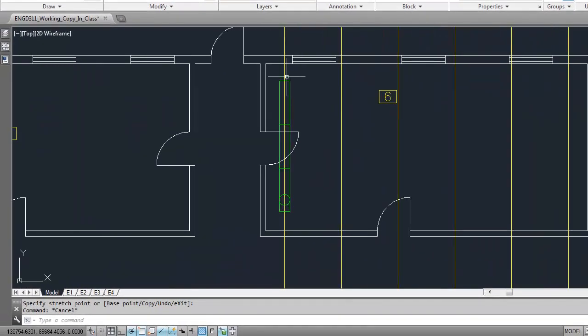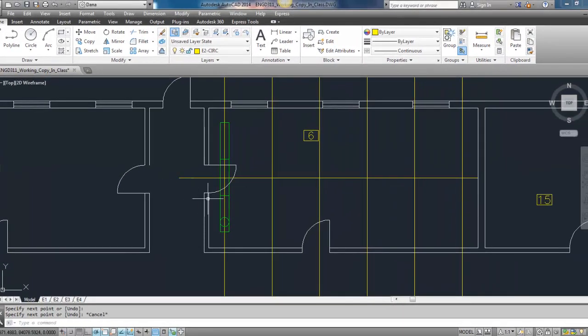We need to be able to perfectly center that group of luminaires, those three, in that space. So we want an equal space at the ends on either side of the luminaire columns. The way we're going to do that is we're actually going to draw a line from the center of the room. So if I can find a point that's from the center of the room, I'm going to draw a line. I'm just going to draw it straight through. And now I'm going to actually center this group of luminaires to that line.